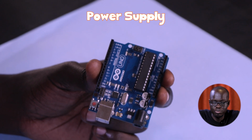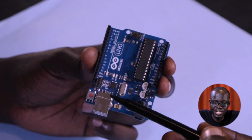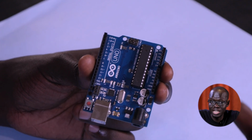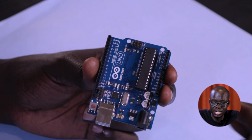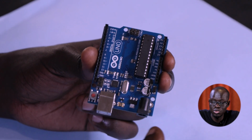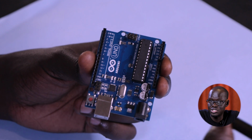So this is where you put in a power charger, right? A power supply. An Arduino board can run directly from your computer, but if you are using bigger electronic components like motors and anything with electromagnets or speakers, or anything that requires a lot of electrical power, then you need to make sure that you have a separate connection for power. Because if you try and connect those things directly to your computer, you can actually risk damaging your computer.